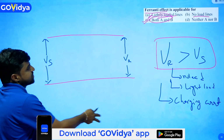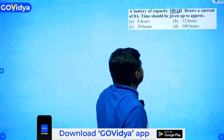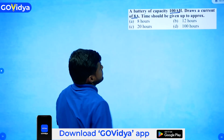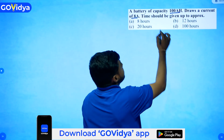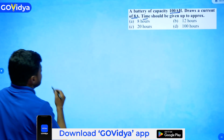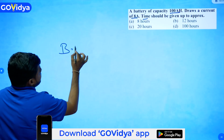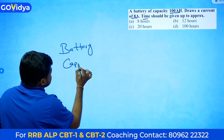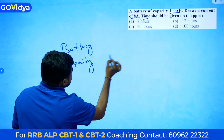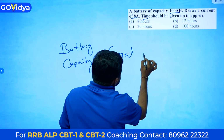Okay, next question. A battery of capacity 100 ampere hour draws a current of 8 amperes. Battery capacity is given and current is given. We have to find the discharge time. We have one formula for battery capacity: battery capacity is equal to current into discharge time.